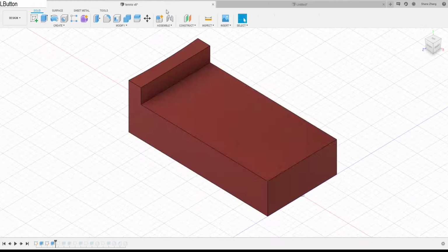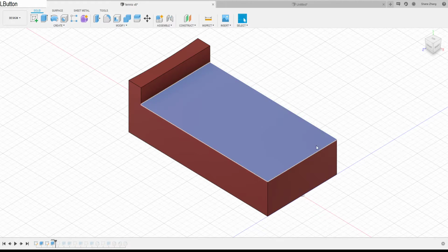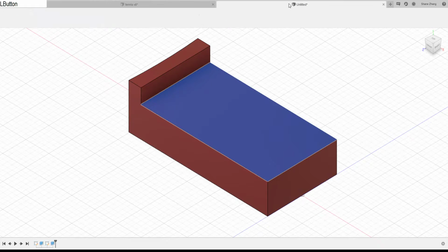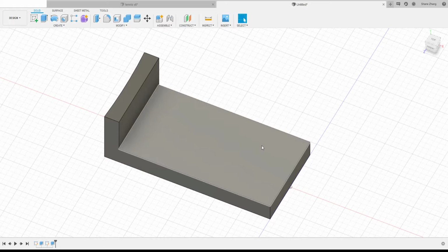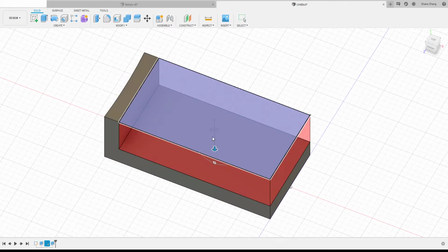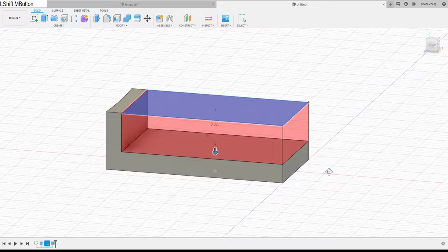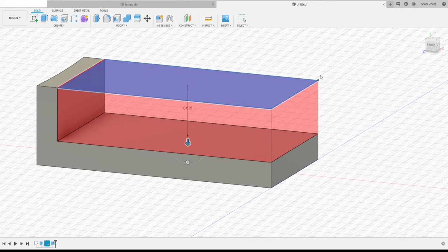Oh, okay. So what happened here is when I measured this piece, I measured from this top plane to the bottom plane. So it's not cutting that. It's 7/8 from the bottom plane. So I wasn't gonna do a subtract, the total height minus 7/8. So there's a way we can just say we want this extrude 7/8 to the bottom plane. So it is a little bit different extrude. So we need to change a little bit of options here.